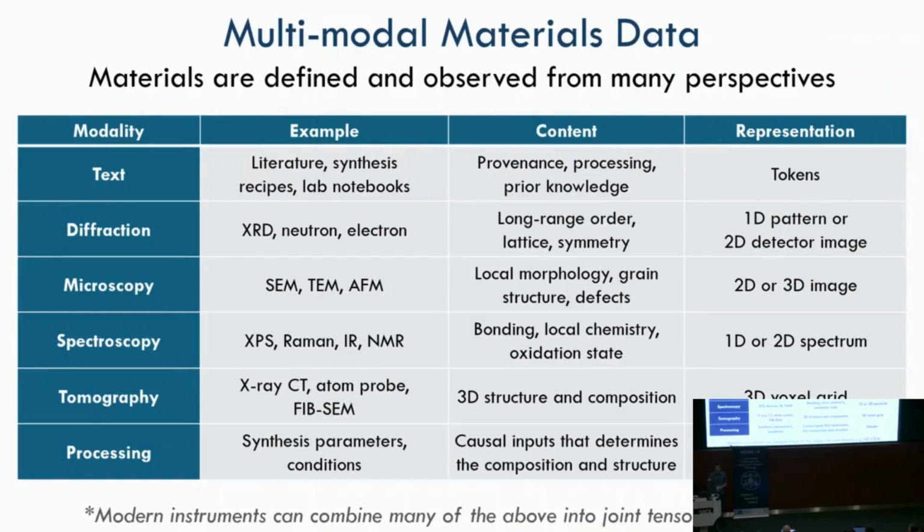And then you have data sets going from 1D to greater than 3D. X-ray diffraction is used a lot for characterizing the structure of materials, but that gives you a low-dimensional representation, whereas if you go to tomography, you're dealing with 3D voxels that are being measured. And then there are many combinations of these, like 4D STEM, that go to even higher dimensions again.